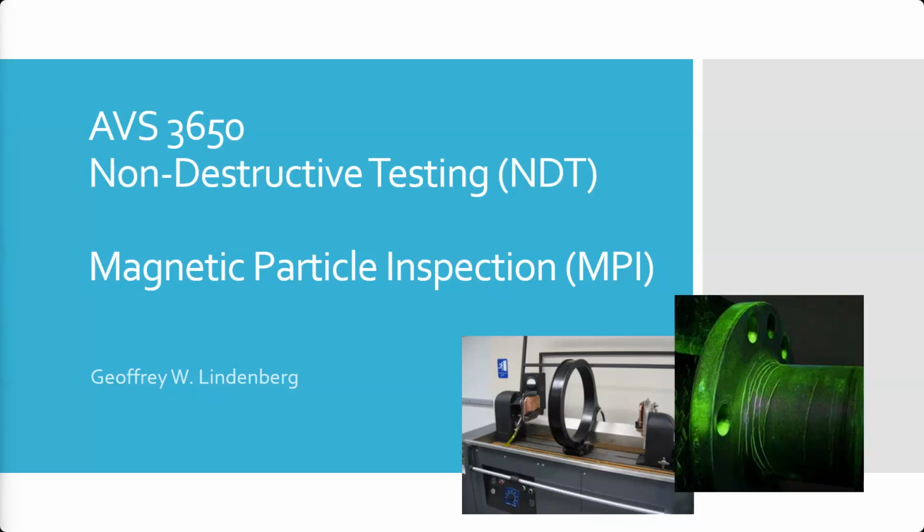So magnetic particle inspection, I just have these pictures here so you can see what things look like. On the right is an object that's had magnetic particle inspection performed on it. We can see where cracks are showing up, these defined glowing lines right here. We talked about relevant, non-relevant, and false indications. Just to discuss those real quick, these cracks would be your relevant indications, right?